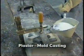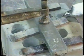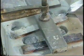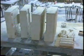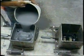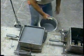Casting in plaster molds is a precision process for aluminum alloy, low-lead copper, and zinc alloy parts. Ferrous metals are unsuitable for plaster mold casting because the molds cannot withstand their high melting temperature. Plaster molds and cores are made largely of calcium sulfate. Besides calcium sulfate, other mold ingredients may be used to improve moldability, reduce porosity, increase strength, and/or control contraction.